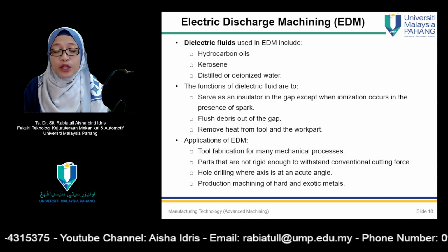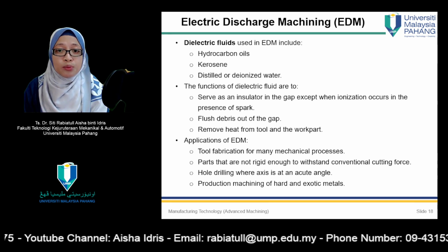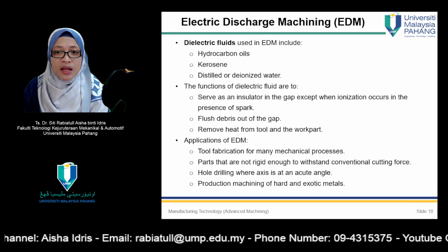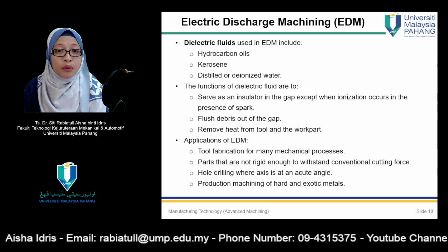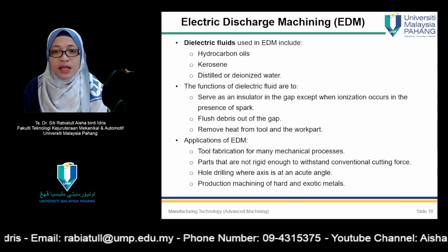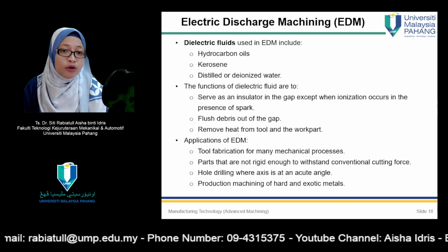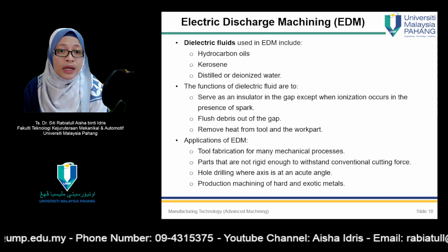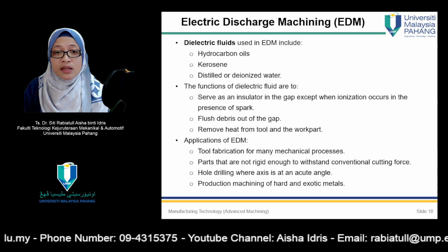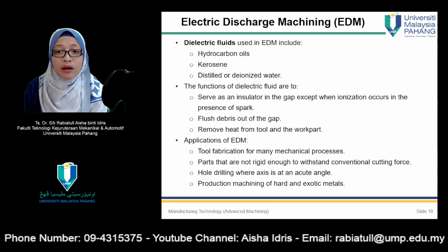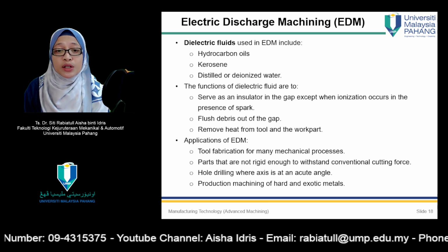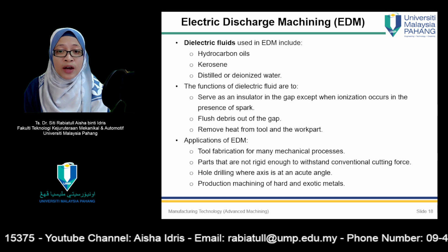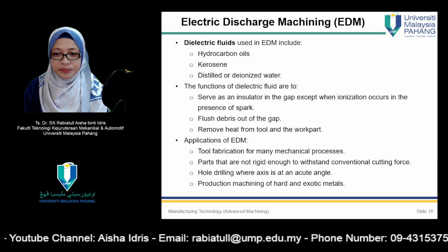For many of the applications, the materials used to fabricate the tooling are difficult to machine by conventional methods. Certain production parts also call for applications of EDM. Examples are delicate parts that are not rigid enough to withstand conventional cutting forces, hole drilling where the axis of the hole is at an acute angle to the surface so that a conventional drill would not be able to start the hole, and also production machining of hard and exotic metals.